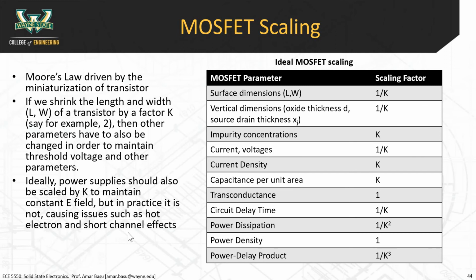Why? Because like we've been scaling down, let's say back in the 70s and 80s, the transistor dimensions were 10 micrometers, right? 10 micrometers was a typical gate length for the transistor back in the 80s. Nowadays, it's on the order of 10 nanometers. So that's going down by a factor of 1,000. The typical voltages used in transistors back in the 80s were maybe something like 5 volts. If you went down in your voltages by a factor of 1,000, what would that leave you with for your threshold voltages?